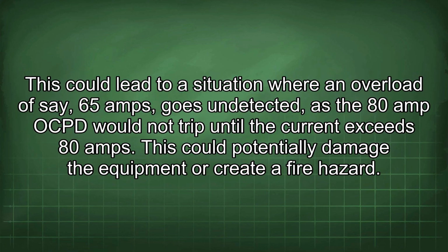This could lead to a situation where an overload of, say, 65 amps goes undetected, as the 80 amp OCP would not trip until the current exceeds 80 amps. This could potentially damage the equipment or create a fire hazard.